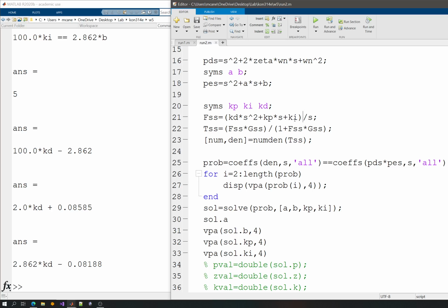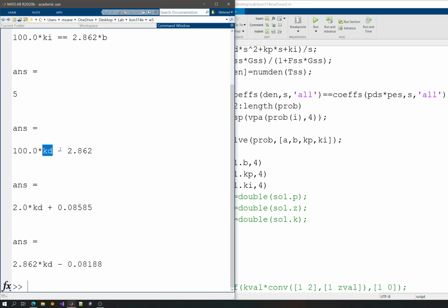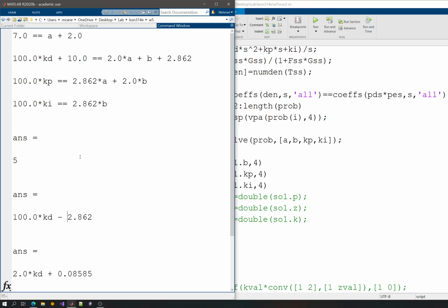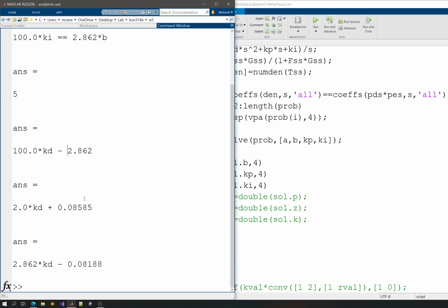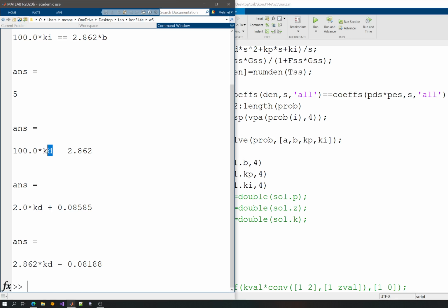Now, poles on the right half plane are causing instability, but zeros on the right half plane do not cause instability, but adverse effects that are not really that wanted in control system design. Now, for a certain KD value, I'm also able to look where my pole is and where everything is. Now, I can see that if I increase B as much as possible, I'm basically placing the pole as far away as possible for B. I'm not sure about the pole, but I'm increasing something in the polynomial, and that is B.